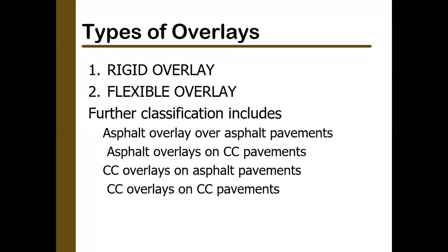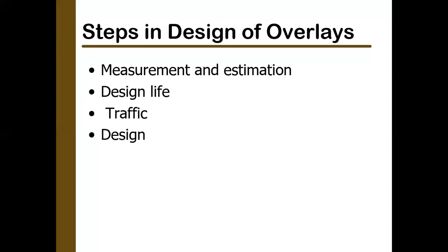So we can classify the overlays into 4 categories: an asphalt overlay on asphalt pavement, an asphalt overlay on cement concrete pavement, a cement concrete overlay on asphalt pavement, and a cement concrete overlay on cement concrete pavement.